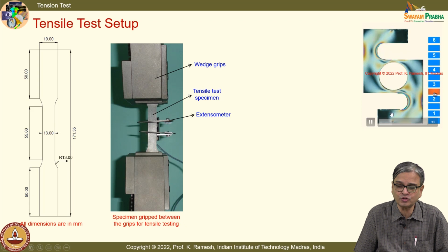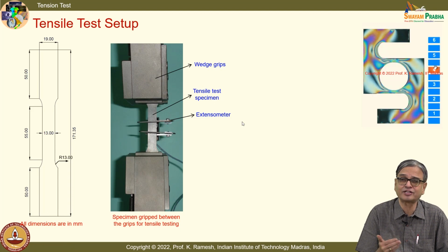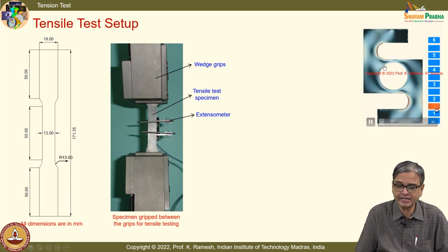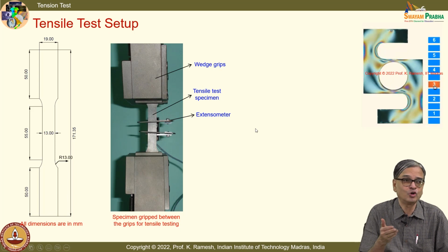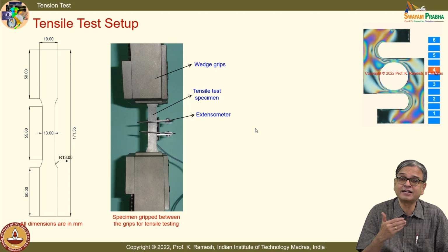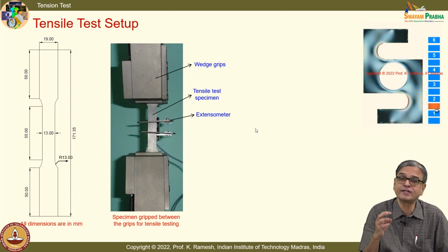When it is subjected to loading, if you perform a test, because these are not coming under your strength of materials, it's difficult to analyze what the stress state is in this. So they put 4 strain gauges, 1, 2, 3, 4, on the inner boundary of this. And because we have discussed that we want to amplify the signal in the case of transducers, if I put 4 strain gauges, I can get 4 times the signal when the load is applied.